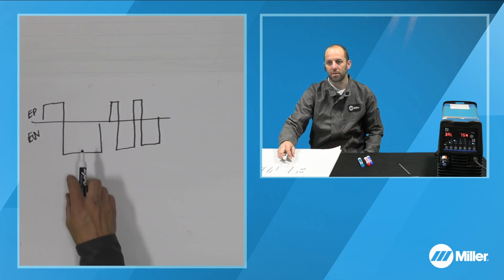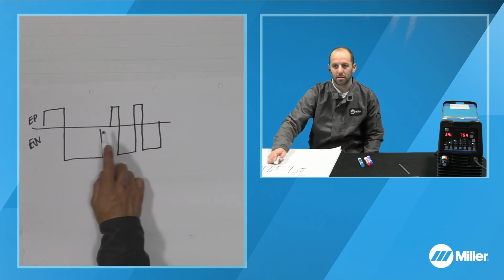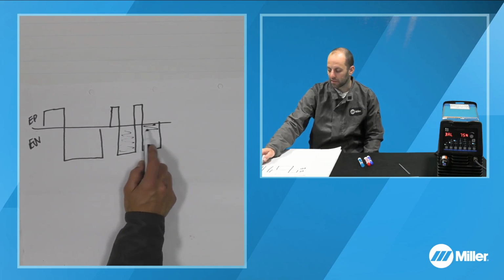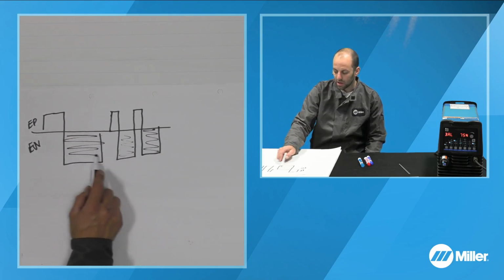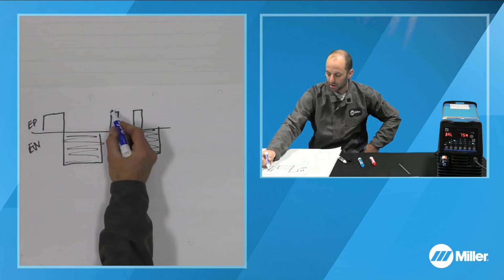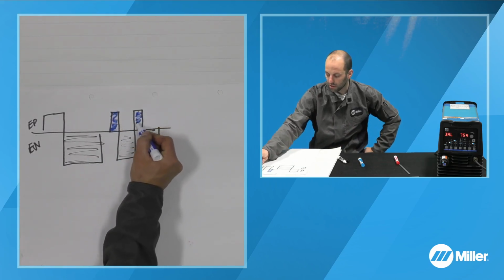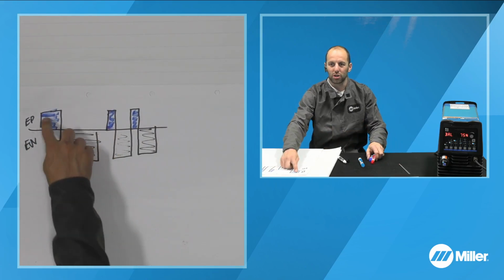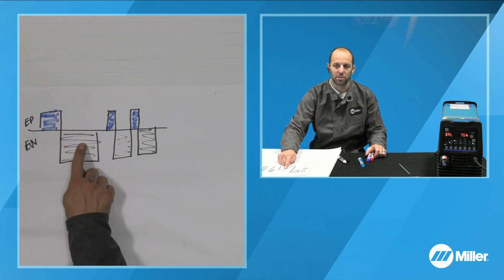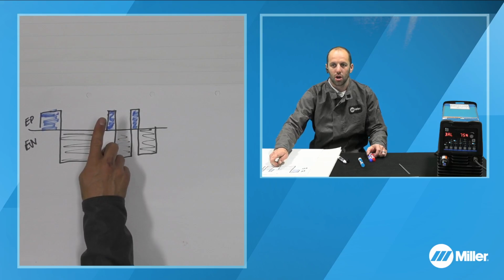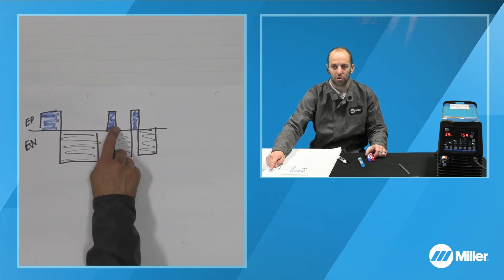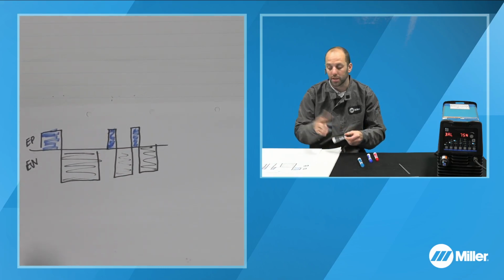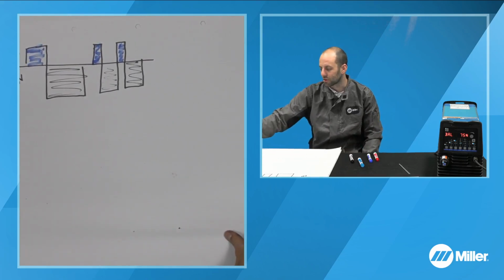So if you were to compare these two, this one on the right-hand side is twice the frequency of the one on the left-hand side. Still the same amount of area in these two boxes as there is in this box. And if we look at these two boxes up here in blue on our electrode positive, those equal the same amount of area there. So the balance or the ratio of our time in electrode positive versus electrode negative hasn't changed. The amount of area hasn't changed. We're just simply hitting more times and switching, crossing this zero crossover point, changing polarity directions more frequently. Hence, kind of the name where frequency comes from.